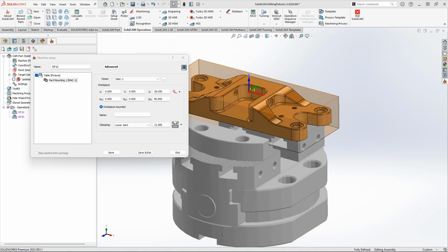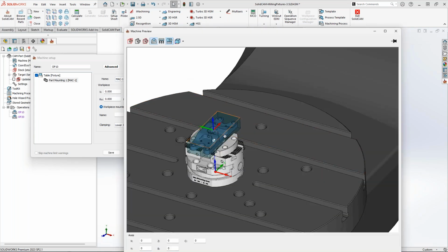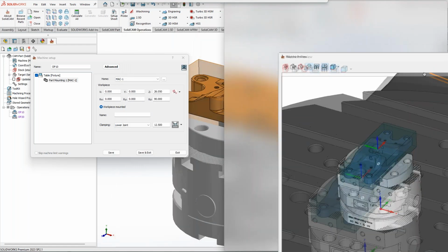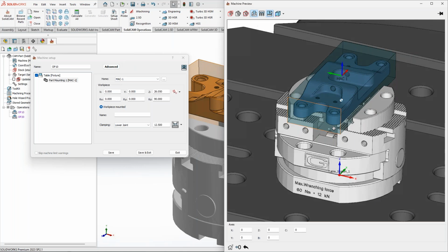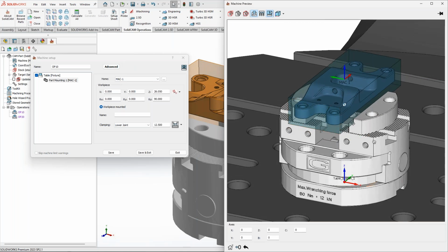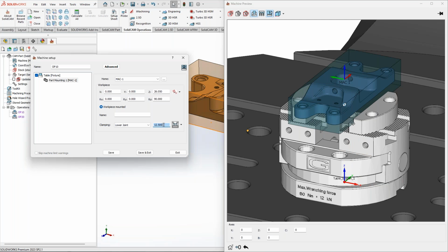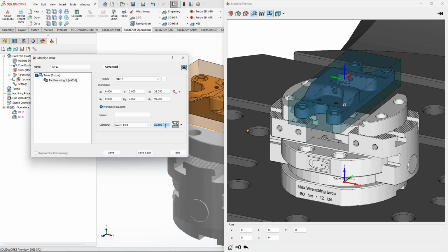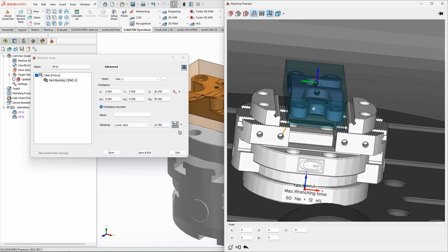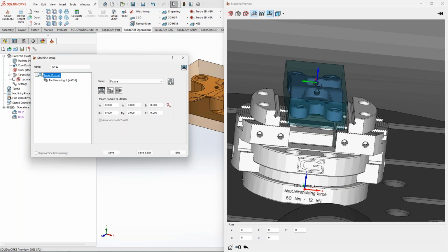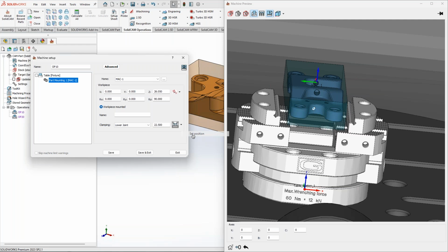So next, oh yeah, something that I forgot to mention. Let's take an example, guys, that I haven't defined this fixture properly, like in XZ plane for the jaws, and I have used some other values, and I'm not able to use this auto close, right? So in that occasions, if you have those kind of occasions that auto close is not working properly for your particular example, you can always use this set position. Let me just turn off this table show and hide. So you can always use the set position.